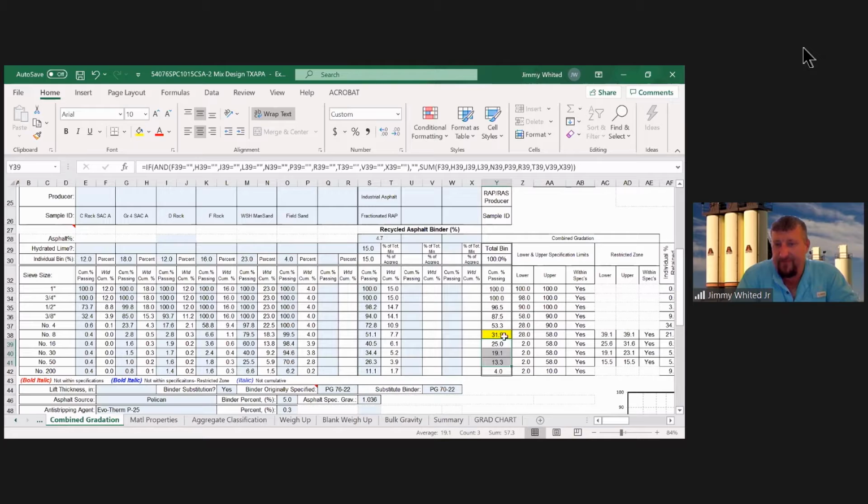Now, when you have this type of mix that has a little bit coarser structure, you start getting repeatability with that Superpave press. That Superpave press does not like fine mixes. So when you start getting the rock in there and you start molding, you start getting consistency. And when you get that consistency, that's how you're going to optimize your bonus money.